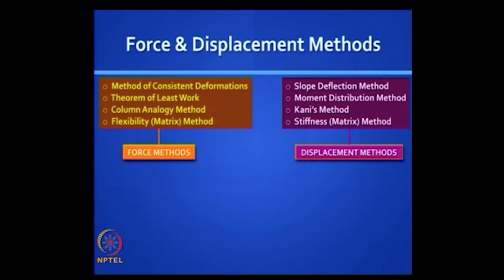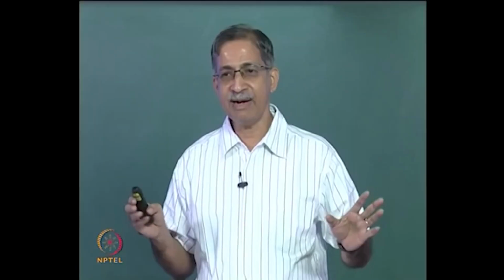We will look later at displacement methods, but at the very outset it is important to know the main differences between force methods and displacement methods. They are both aimed at analyzing indeterminate structures, completely different paths. Both are very interesting. Displacement methods are probably better suited for computer application, but can you tell me what are fundamentally the main differences between force methods and displacement methods?